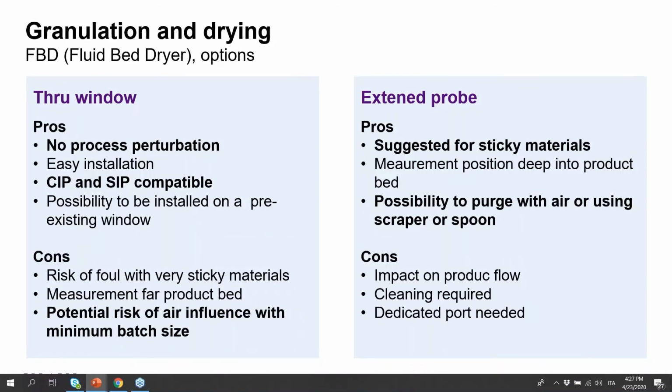This is a good point: when should we work through the windows and when should we work through an extended probe? It's very hard to give a general statement. Normally, when I can, I prefer to work through the windows, because it allows me to avoid a process perturbation. As I said, I can clean the windows as I like, and it's very scalable and easy to use.